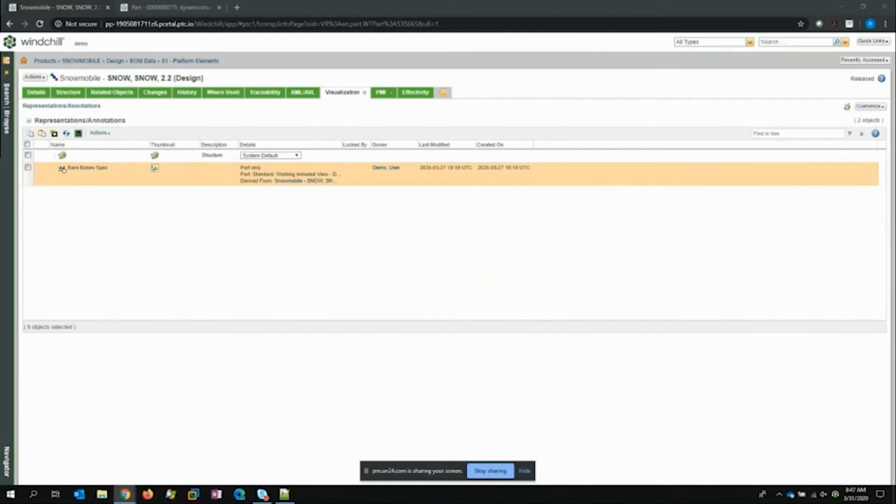If there's an owner link between an EPM document and an assembly, it will actually get stored against the part, not the EPM document. So in this case, with this top assembly, the top assembly and subassembly will store the representations. But because this bottom CAD model is not in my part structure, it will actually store the representation against the CAD model. So that's key to understanding how all of this stuff works.